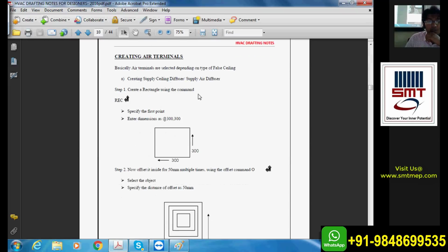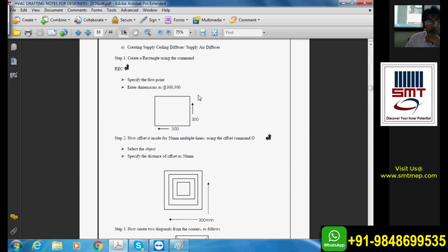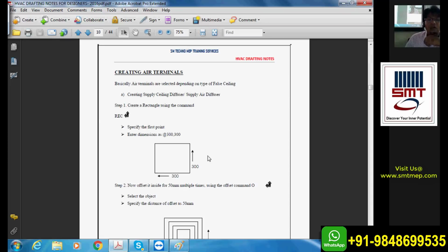Now from page number 8 is what I'll be doing tomorrow, because that will need me to create the air terminals directly. I'll show that on the CAD software. We'll start dealing with individual appliances first, like how to create diffusers and grills, the reducers, the machine, the flexible duct, the trouser piece, and how to apply your elbows, etc. Then we'll go into the main project study, which is called SLD and DLD of the airside project.